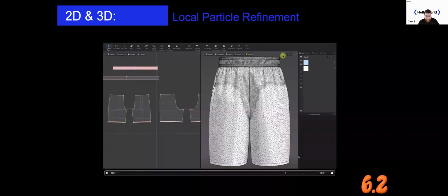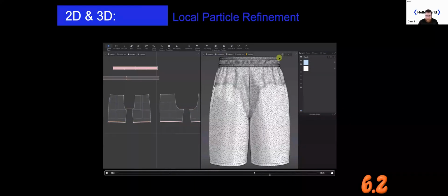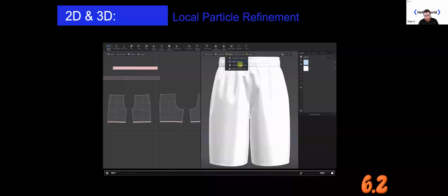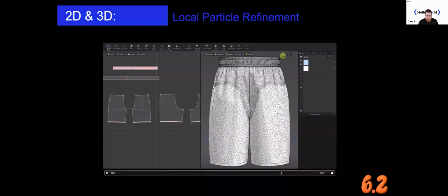And you can see the way that this works. We've actually gained a little bit of detail in the wrinkling where the pant legs, the short legs meet the waistband. And this is the benefit. If you've ever heard me talk about polygon counts and quality before, this is why. When you increase your mesh density, or you increase the number of triangles that are here, you can see more detail. That does tend to come at the expense of speed.